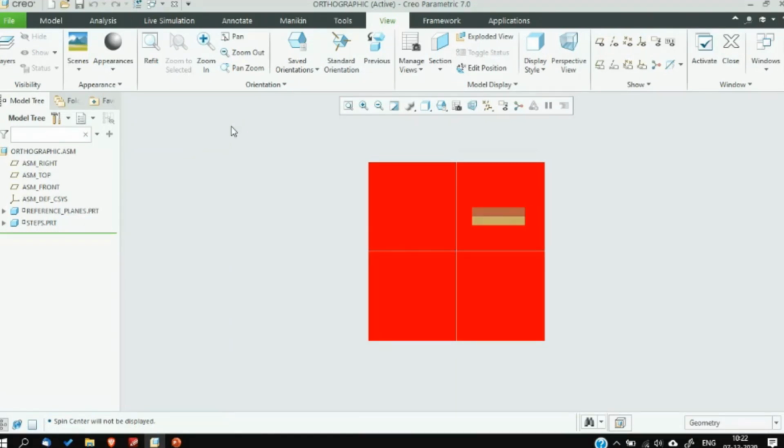Otherwise, the front view is what you get if I project rays of light from a parallel source onto the object and make the shadow fall on a vertical plane; that shadow is my front view. So the front view is the view we see when we look straight into the object.